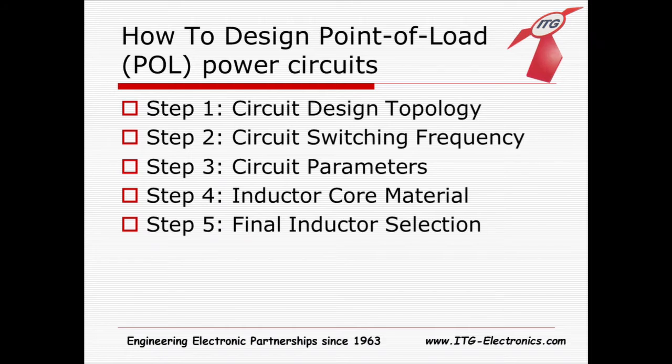These are going to be the 5 steps of designing a POL power circuit. First, we're going to take a look at the design topology. The second is determining the switching frequency that's most appropriate for your application. Third are the circuit parameters. Fourth is the inductor core material. And the final step is the final inductor selection.